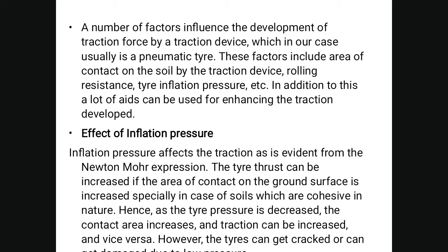A number of factors influence the development of traction force by a traction device, which in our case is usually a pneumatic tire. These factors include the area of contact on the soil by the traction device, rolling resistance, tire inflation pressure, etc. In addition to this, a lot of aids can be used for enhancing the traction developed. Now the effect of inflation pressure.